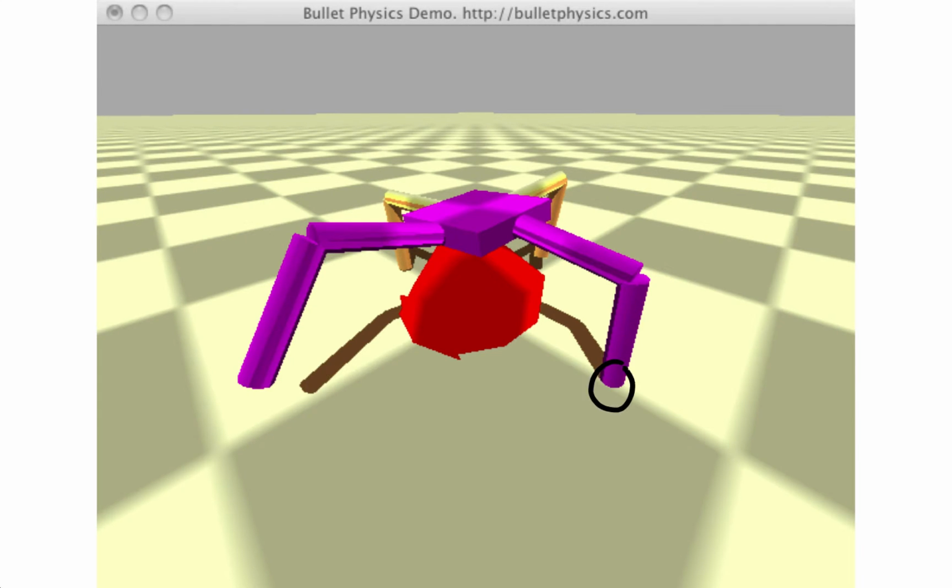are touch sensors that we're going to place at the bottom of each of the 4 lower legs, or at the robot's feet. These touch sensors are going to fire whenever the foot comes into contact with the ground, and will fail to fire whenever the foot is off the ground.